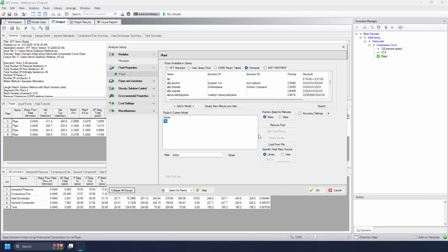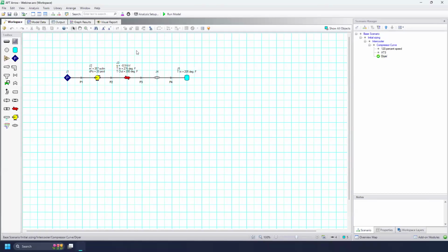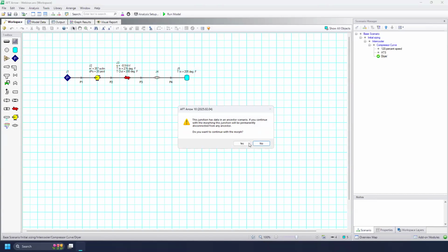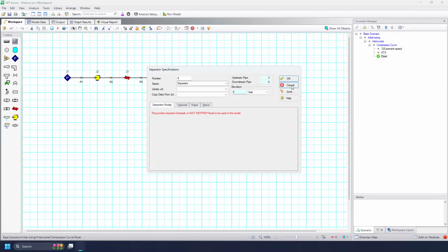Here, I'm not setting it up as a mixture, but just showing you how you do that there. And you would want to use this separator here for any mass that's leaving the system. So I can morph this general component into a separator. I need to set up the mixture in detail, but essentially you would have some mass flow of a given part of the mixture. The steam in this case would be pulled out of that, and you would have just the air downstream.